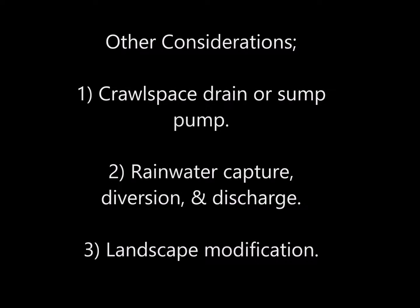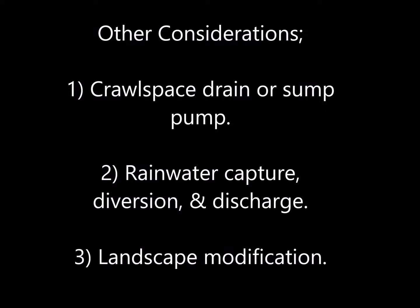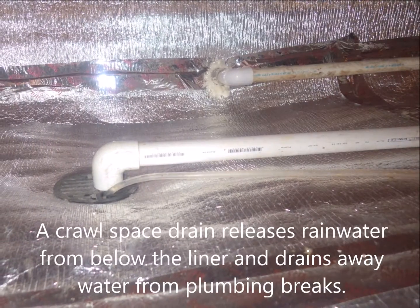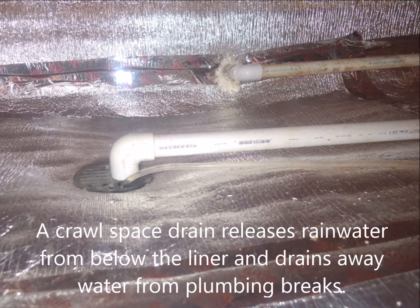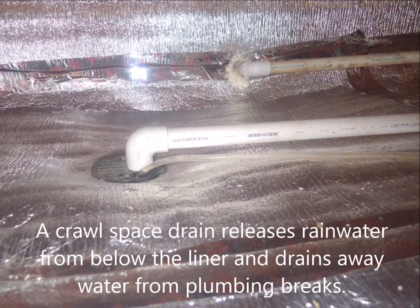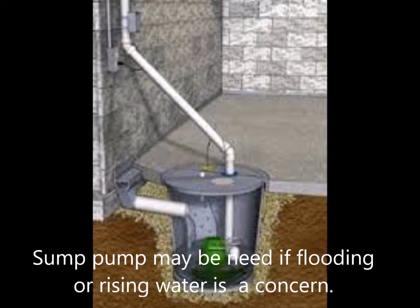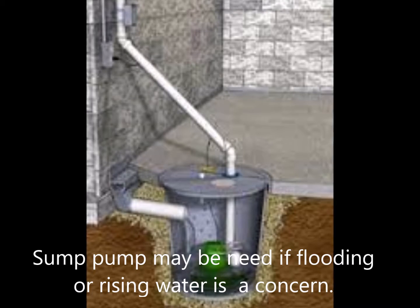Other considerations may be a crawlspace drain or sump pump, diverting rainwater, as well as landscape modifications. A crawlspace drain will release rainwater from below the liner and drain away water from plumbing breaks. A sump pump may be needed if flooding or rising water is a concern.